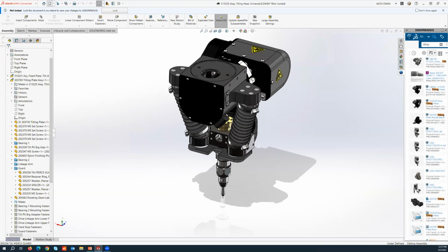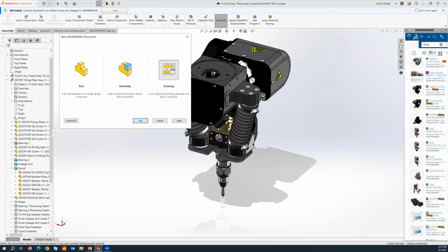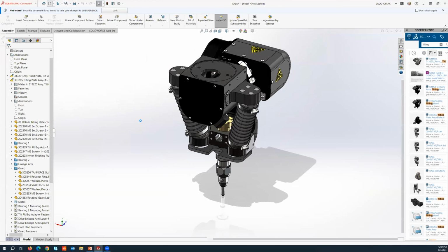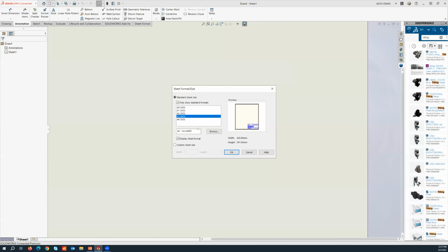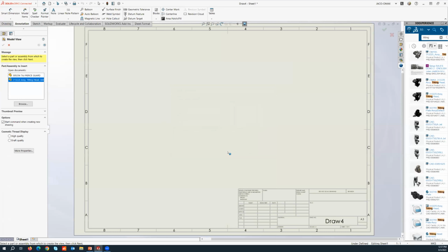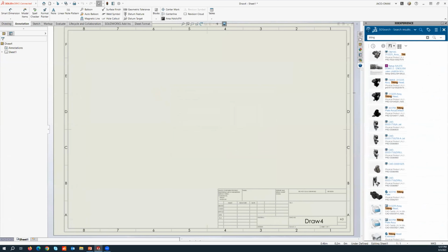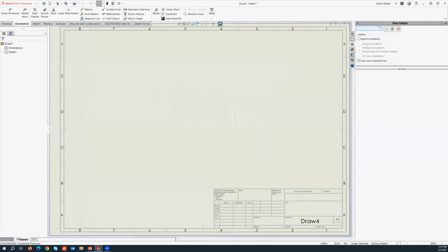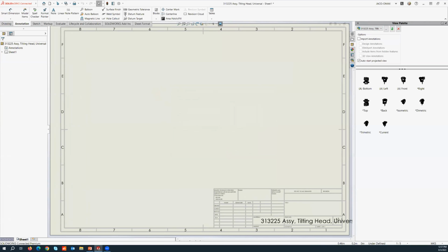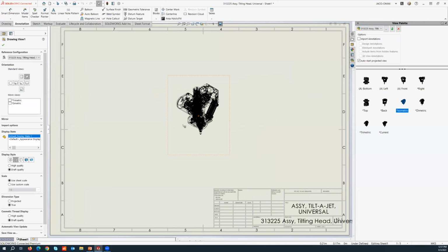So lastly, what I want to show you from the CAD side before we go to the presentation is, okay, I have this drawing now, but I need to prep this for manufacturing. So back into my drawing view again, just going to accept that. Go into my drawing tab, select this assembly for this instance, and I want to create an isometric view. Again, just drag and drop.